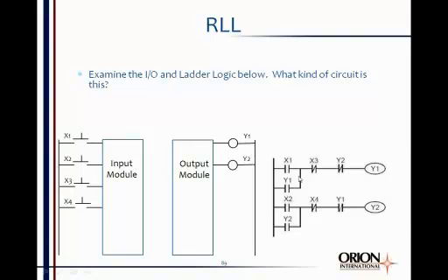Let's see if we can figure out how this operates. Well, if I were to press X1, if I were to push that button X1, that's going to close this contact over here in the top rung of the relay ladder logic.